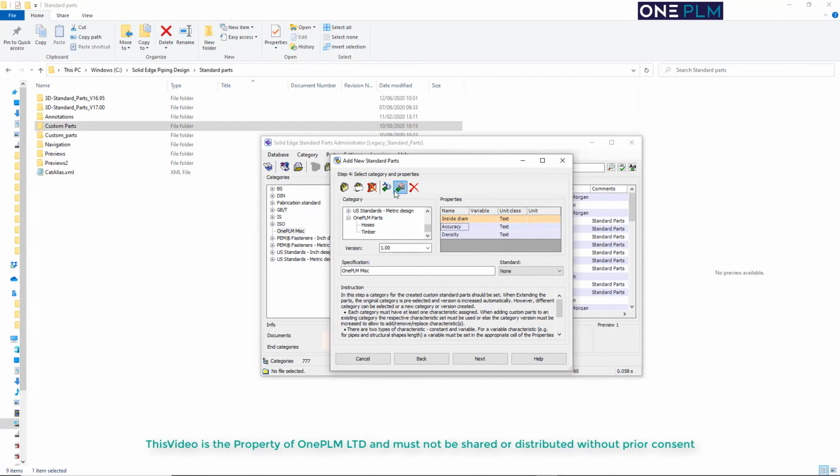So next, I want to create another one. For this characteristic, there's lots of different options, but if you just start searching for the option that you want, so if I start searching for pressure, it's going to give us those, but I know this is called nominal pressure. So if I go and find nominal pressure as pressure, I can then choose this as bar as the option. And then we need a third one for the type of fluid we're going to use on there. You can see there's lots of different choices on here, so it's just trying to find something that's going to be appropriate to what you want.